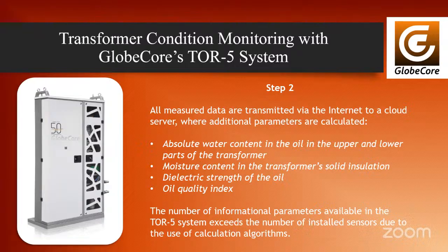The most useful value is the Oil Quality Index, OQI. This number goes from 0 to 1, where 1 means the oil is in proper condition and 0 means the oil is badly aged. The OQI is linked with important aging factors such as acidity and surface tension. This makes it a strong tool for checking oil health without laboratory tests. In short, OQI gives operators a clear and reliable sign of oil aging and transformer reliability directly online and in real time.